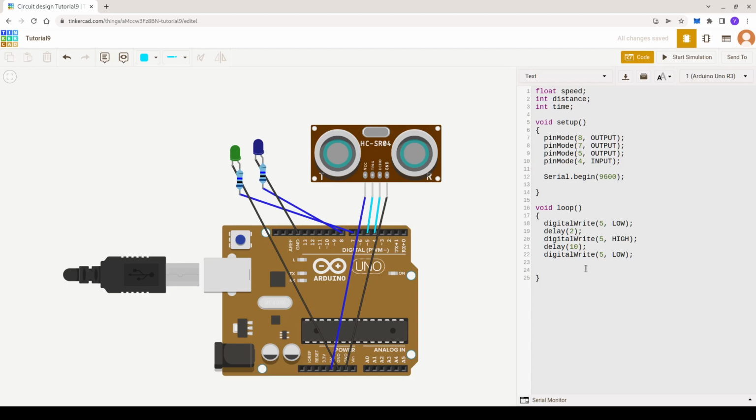So what I'm going to do is calculate the time. Now we are using pulseIn, pulseIn, and which pin, HIGH? The receiving pin, right? Now, what does this mean? We are just getting the value of time. The receiver pin has received it, and now it needs to know how much time it will take. For that, it is just like a timer. We are just turning the timer on.